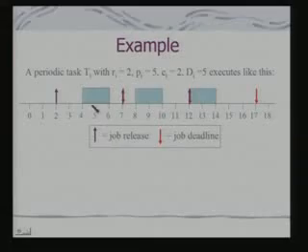So this is an example of a periodic task. You find the task gets released at regular intervals, and what I have shown is the deadline coincides with the release, because the tasks related to these data must be finished before the next job arrives, and this is true for the majority of sampling-driven tasks, because before the next sample arrives, the previous sample should be processed.